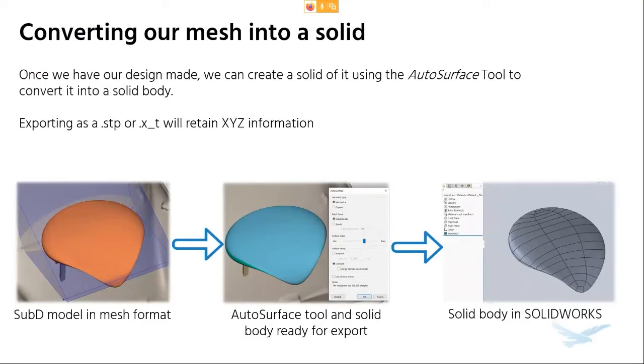And this is something that was really handy when it came to this rapid prototyping design, because there are a lot of times where I will export out a model or a mesh, bring it into a different software and find out that it's not in the right position, and I have to figure out where it is in the XYZ space. Whereas in Freeform, it retains all that information during the export. So I can take that mesh that I turned into a solid out as a Parasolid, bring it into SOLIDWORKS as an imported body, and it knows exactly where it is, so I can automatically align it to the car.